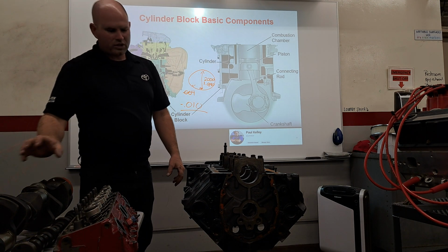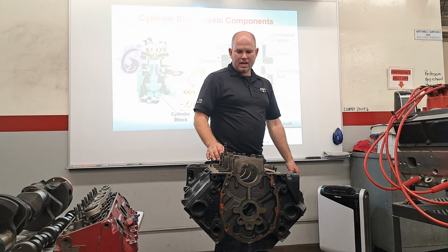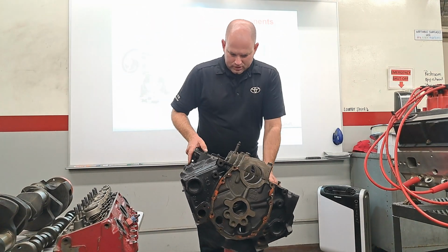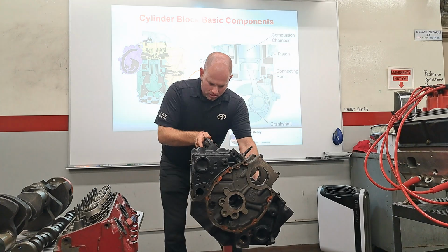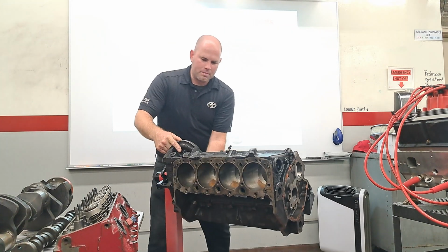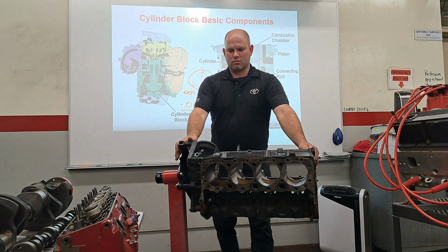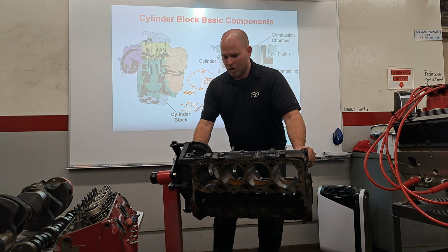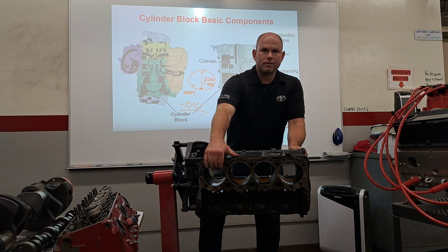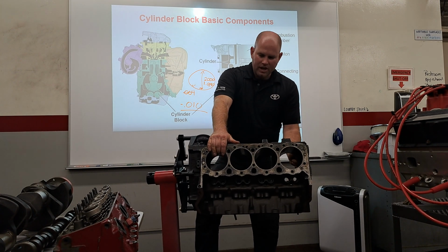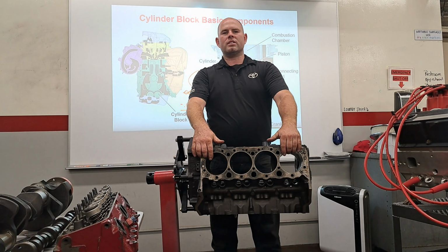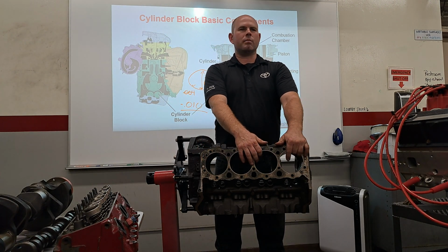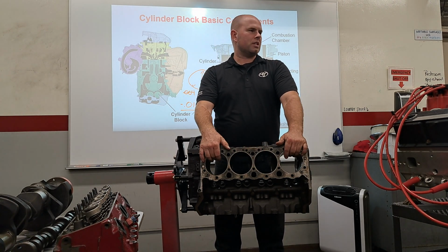And then, let's say we look at cylinders. That's the next thing we need to discuss. When we're talking about engine rebuilding, a lot of our concern is right there in the bottom end with those mains and rod bearings. That's very common. But also, we got some concerns about cylinders. So here you can see we've got a V8. Now, are these cylinders good or bad? Does this need to be machined? Can it be honed? Does it need to be actually bored over? You tell me. I don't know.